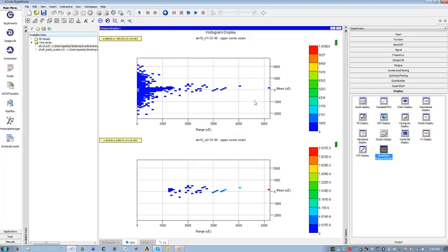This plot down here is showing me what we call the damage histogram, and that is simply a collection of cycles as well, but the cycles that it's showing here are the cycles from the rainflow histogram that actually caused damage. These cycles way down here, where you see this heavy collection of cycles, are really, really small in range. They're so small, in fact, that they don't even cause any damage. So there's a whole bunch of those. The good thing is none of them cause damage, so it's not going to be a problem for us. What we can see, though, is that there are quite a few that do cause damage.